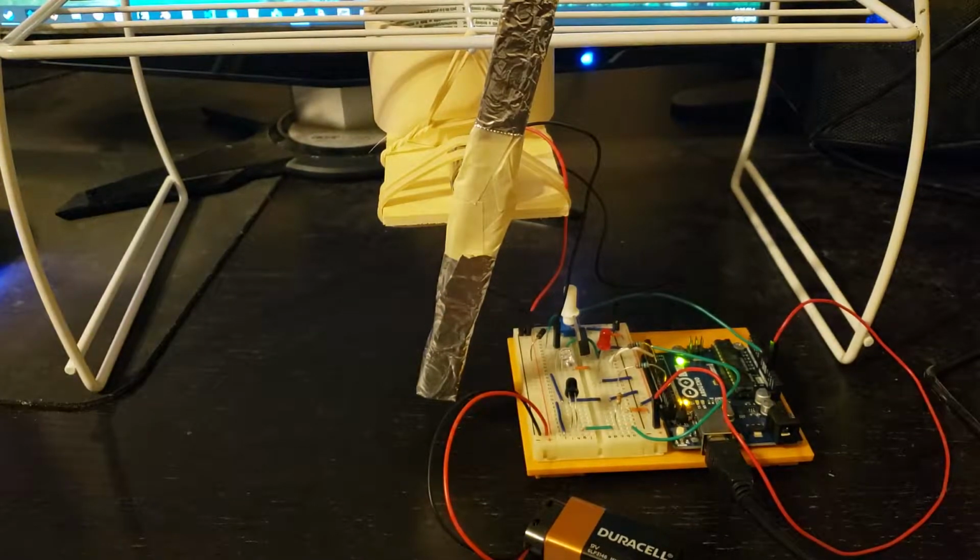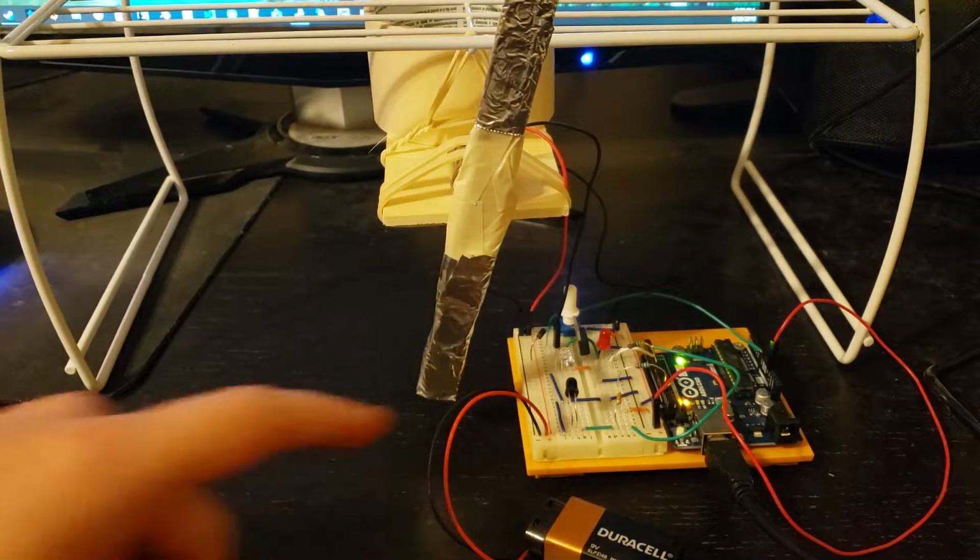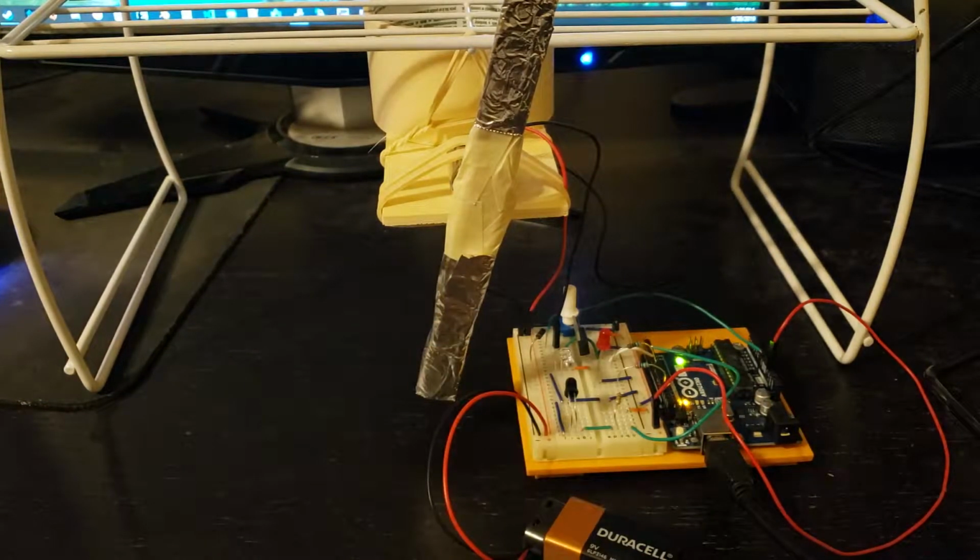I found out that this can be done using pulse width modulation, which several of the Arduino Uno's digital pins are capable of doing. They're labeled PWM, and they have a little tilde symbol next to them. Pulse width modulation mimics an analog signal by setting a pin's output value between high and low in intervals. This interval is dictated by the value written to that digital pin, an 8-bit value, so a value of 0 means the pin will never go high, 127 means the pin will be high 50% of the time, and a value of 255 means the pin will always be set to high.